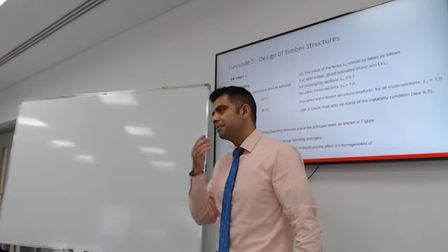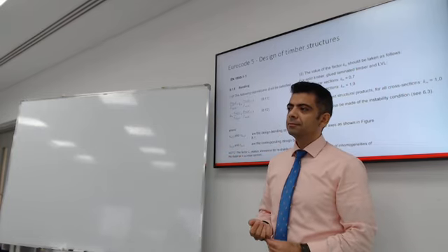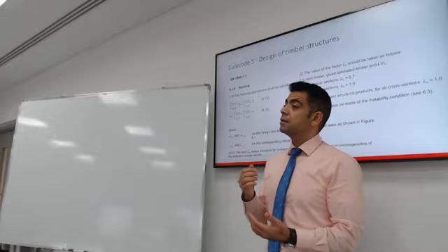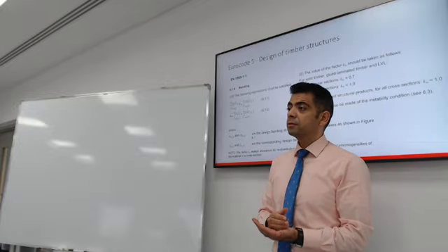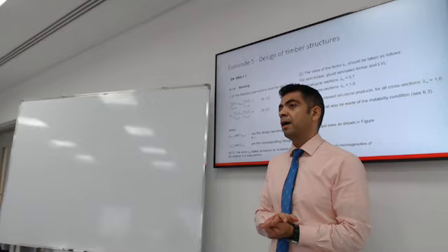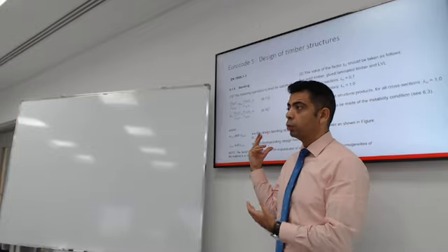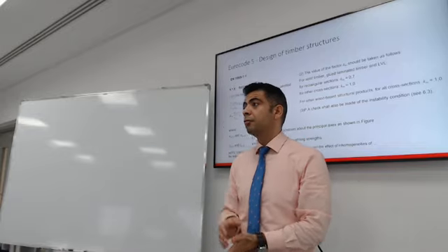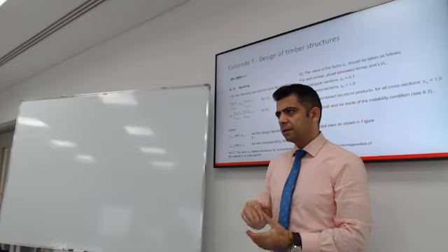Go ahead. I have a question. For timber or wood in general, why do they use it when it has so many disadvantages? Because if it's ready, affordable and fast to build with, it's approved as a construction material. If it's going to do the job and you can safely build with it, the code will regulate ways to deal with the disadvantages of wood, so you can use it as a construction material. Does that make sense? Yeah, it makes sense.